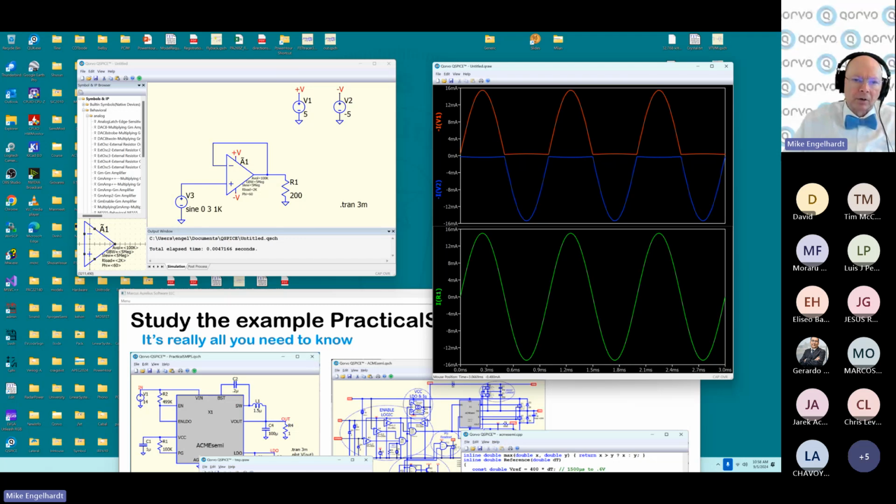Basically, what's happened here is that I have a native circuit element that is a transconductance, except that the current doesn't come from ground magically. It comes from the supply rail, so it automatically switches over from the right rail. And then I've used a few of these inside this rail-to-rail op amp to make an arbitrary rail-to-rail output op amp. So that's going to be very useful for you.